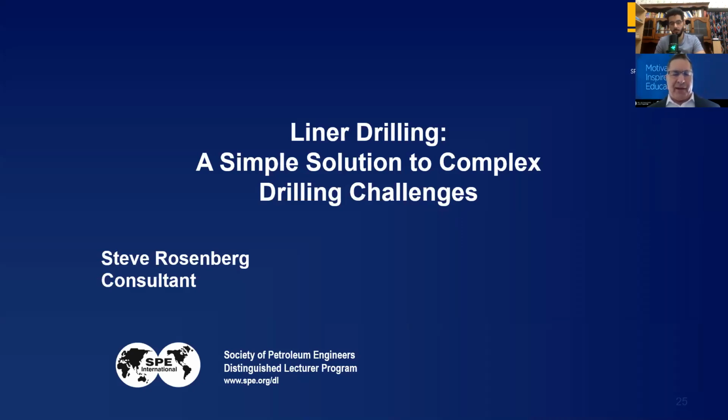Yeah. No. Thank you so much for answering my questions. There's really no downside if you use it for the right application. Yes, things can happen. Unforeseen things can happen, but you have to do a proper risk assessment to address these things so there are no surprises during the liner drilling application. One of the biggest things, even before you start, the first thing you do when you pick the bit up is look underneath to make sure the nozzles aren't plugged.